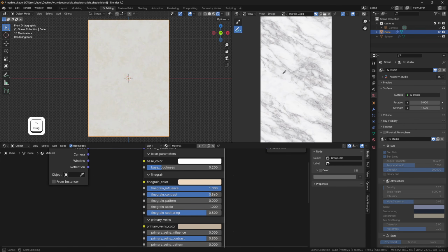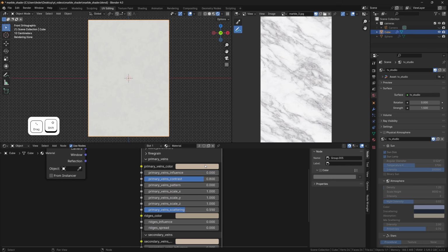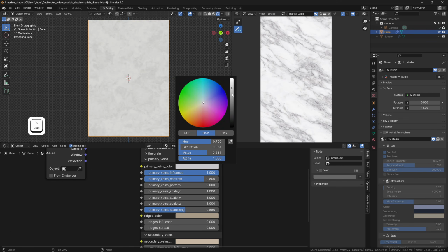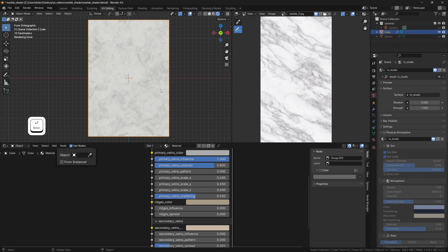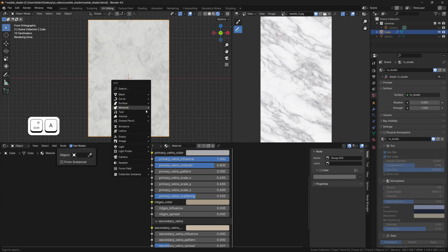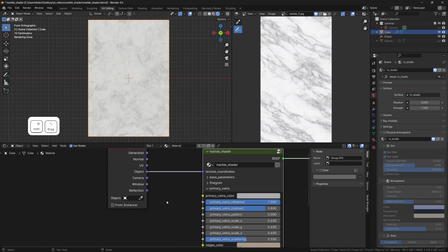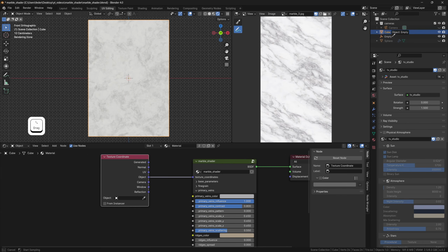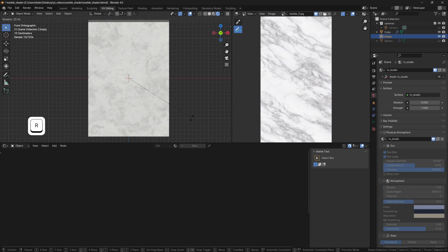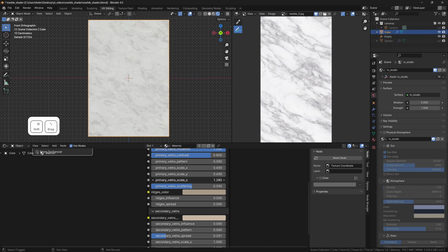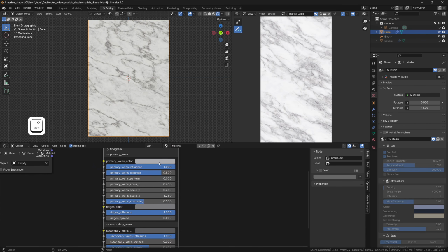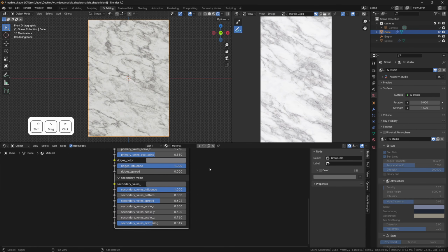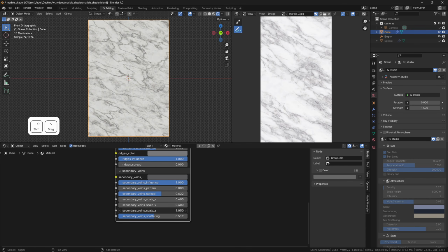I'll use the reference to sample colors, while I'll progressively enable the different layers one by one, manipulating the respective parameters as I go. One of the advantages of using the object option in the texture coordinates node is that, well, we can actually use an object to define the orientation and scale of the patterns as a whole. As such, I'll add an empty to the project and I'll target that empty from within the texture coordinates node. In this way, by simply rotating the empty and by scaling properly along the relevant axis, we can mimic the diagonal orientation of the original veining pattern in the reference. I'll apply the same concepts also to the ridges and to the secondary type of veins, and it will be then just a matter of playing around with the different parameters until we reach the desired result.